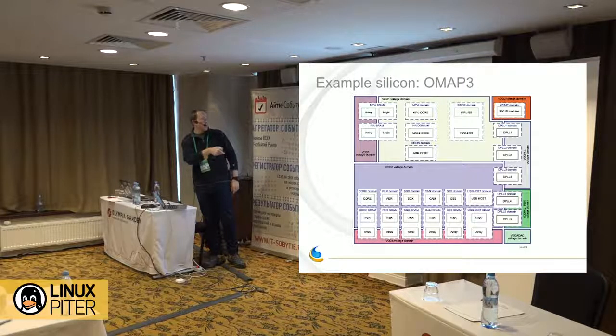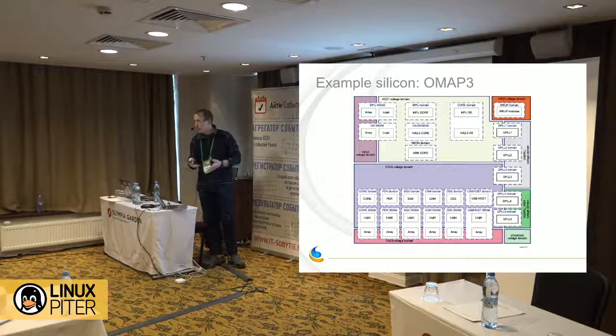So you can see that a lot of times things get grouped together. Like we have this one giant voltage domain that includes the ARM CPU performance as well as some of the multimedia accelerator performance for doing video acceleration, video decoding, video encoding, things like that. And some of the other domains are put together in a logical way. Like you can see the display subsystem is sharing a performance domain with the camera subsystem. It kind of makes sense, since their use cases will probably have them both running fast at the same time, for this particular chip.